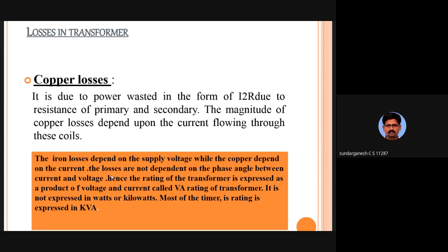If you are asked for the principle, you should explain the principle of mutual inductance. The principle of mutual inductance is employed in the transformer. The voltage is applied to the primary winding, so the flux will interact with the secondary winding. The secondary winding will produce an EMF. If the secondary winding has a closed path, it will produce a current. So this is the working principle of a transformer. Next one is losses.